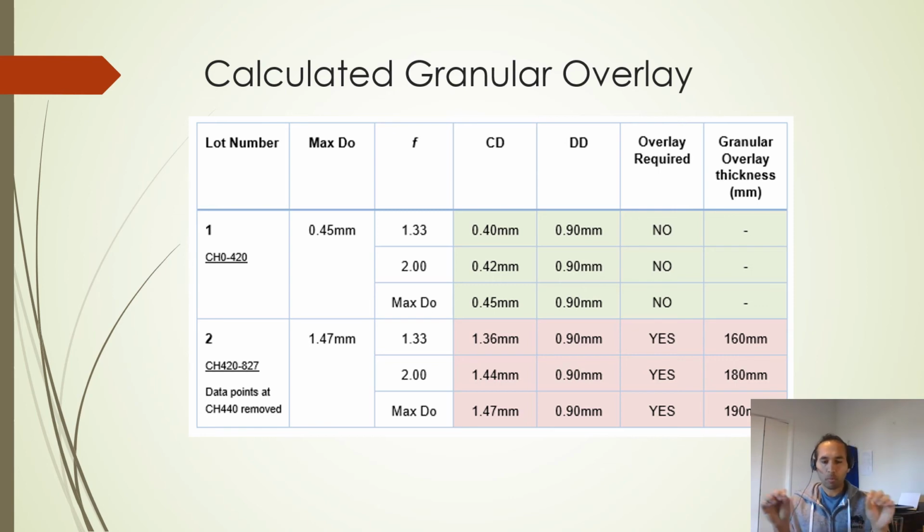So if we adopt the 190 mil across chainage 420 onwards, we're solving the concern of subgrade rutting, so to speak, based on Austroads methodology.